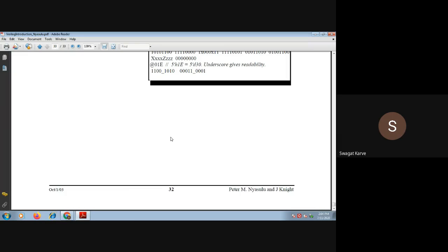Then we came to the different small sections of combinational and sequential logic. We studied the linear feedback shift register, simple combinational designs like multiplexers, then counters and adders, and how you can design them. These are the different codes that we studied in Verilog. And whatever code we wrote in VHDL, such as the comparator, full adder, multiplexer, and 3 to 8 decoder, the logic will be the same, but with different syntax. By using the Verilog syntax, we can program that in Verilog also, right?